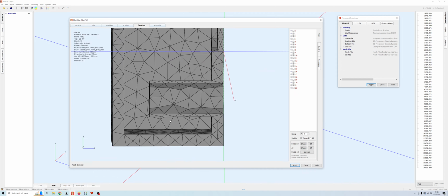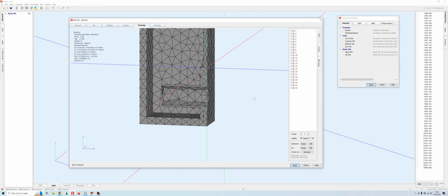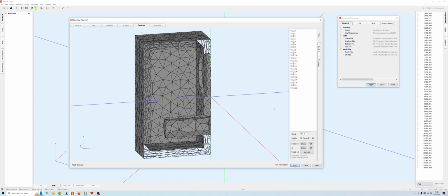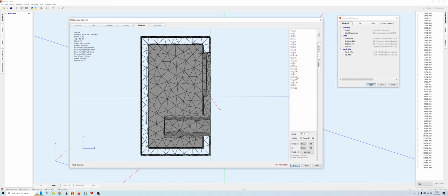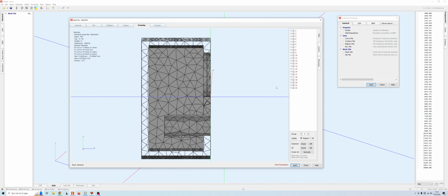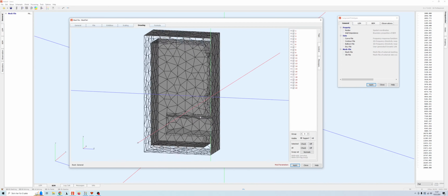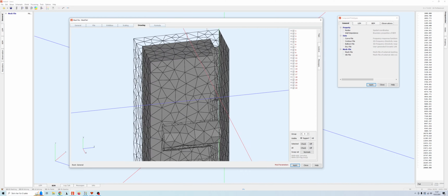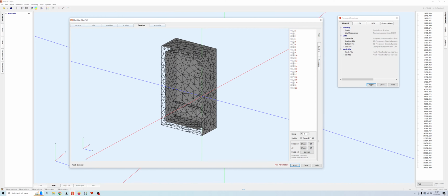Now, the first thing we want to do is take advantage of symmetry. Because of that, we do not need these parts here, because these are going to be inside of the speaker anyway. I can see here, this is tag 15, so I can remove this. I can also remove this, tag 18, and this one, tag 6. Now we have removed these, and this is fine. The cabinet is ready for simulating, so we can just click Apply and then close.